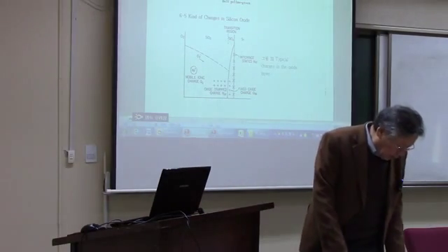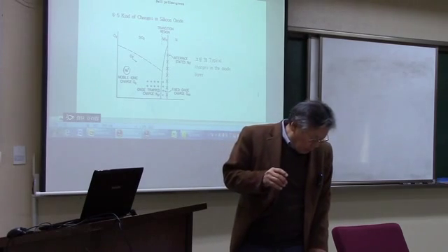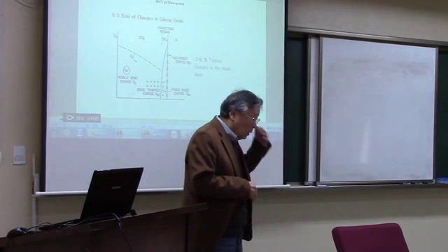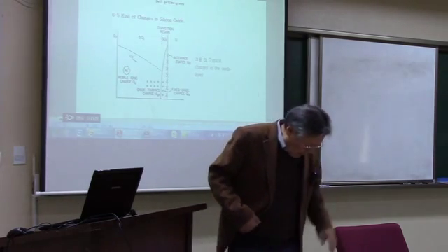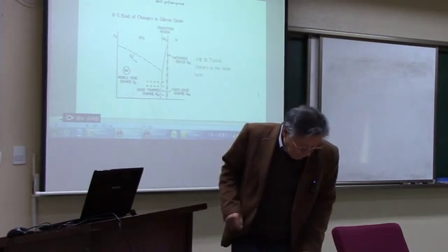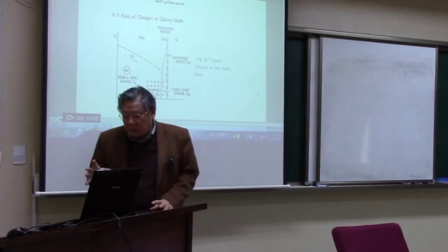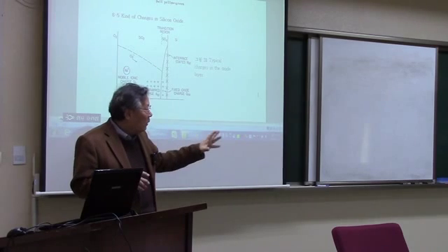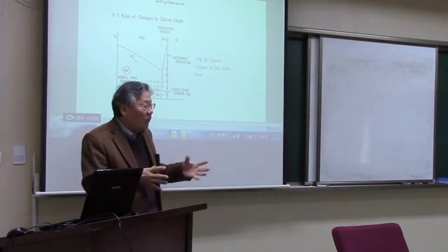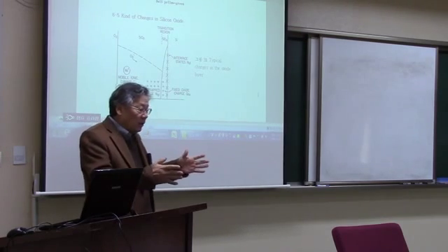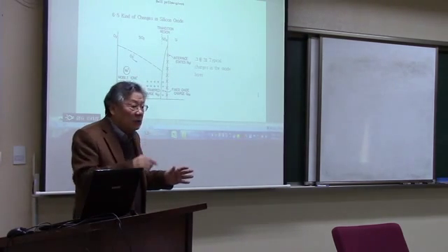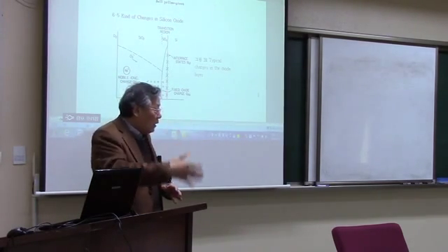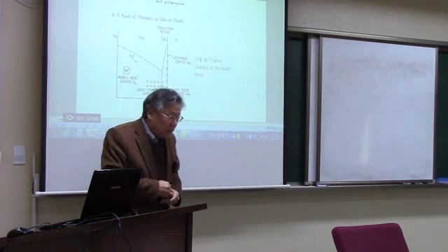Continue the discussion about the oxidation of silicon. Okay, we start with the Deal-Grove model to explain the oxidation behavior of silicon, and we have two constants related with the oxidation process in the silicon. One is the parabolic rate constant, which is related to the diffusion coefficient of oxidant inside the oxide, and the linear rate constant, B over A, which is related to the surface